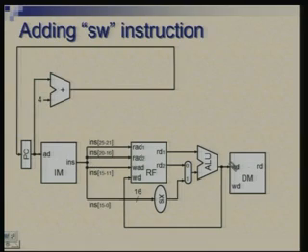So, this part takes care of inputs for data memory, the address input in particular. So, it comes from here, and inputs of the ALU are also arranged now properly. Okay. To complete the picture, we also have to make sure that the data from register file goes to the data input of this memory. Okay. So, where does it come from?